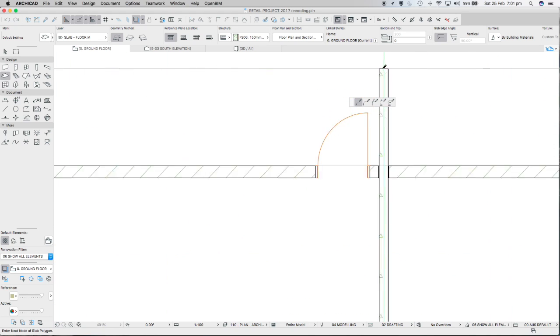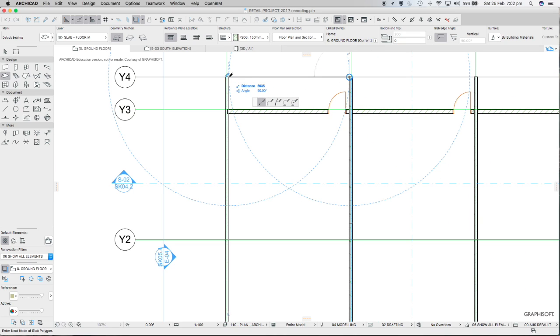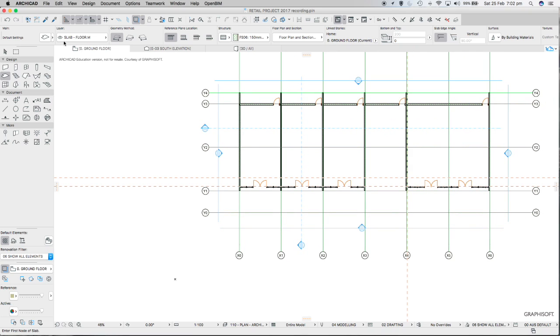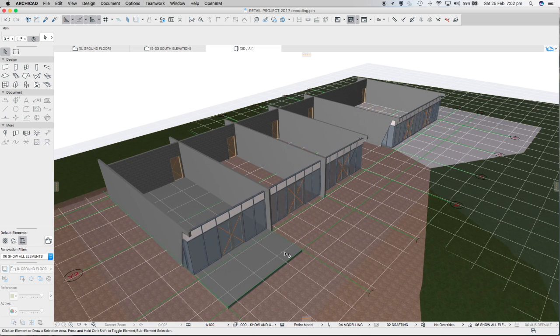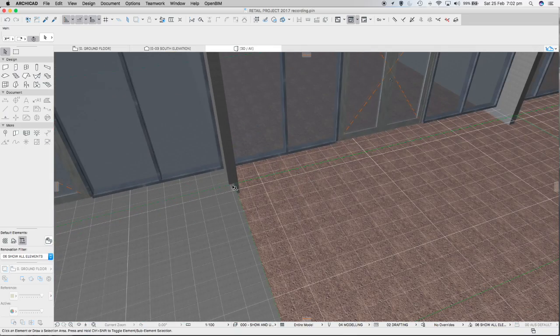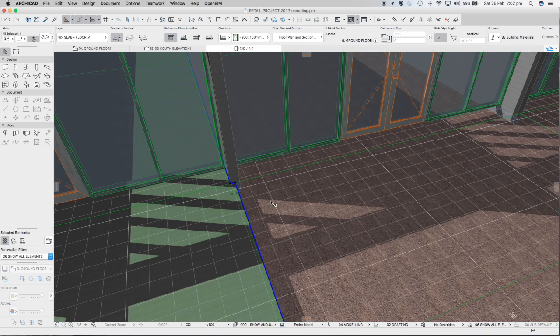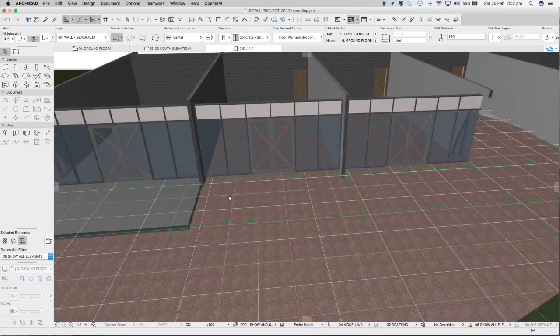And that'll come right out to the outside, because those concrete block walls are sitting on top of the slab, so we could do the slab underneath there. So I've just placed that slab in that location. If I now switch back to that 3D view, so there's the slab, and you'll see that I've placed it along the centre line of the concrete tilt-up wall, but it zigzags around the shape of the wall so that the wall can continue to go straight down onto the footing, to the bottom of that slab level, basically.